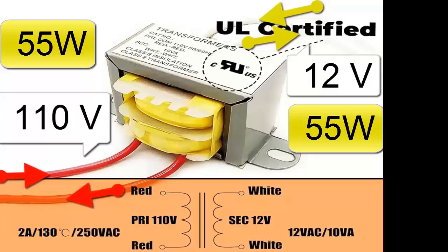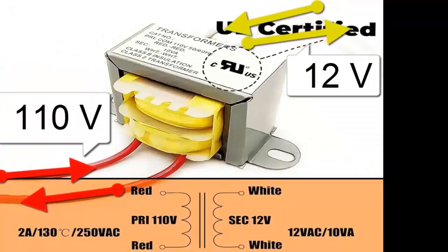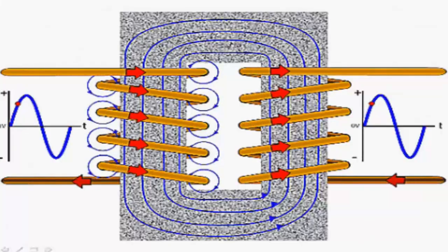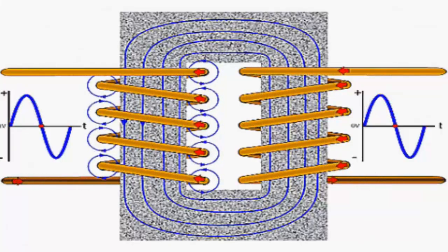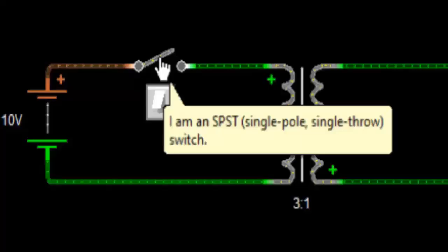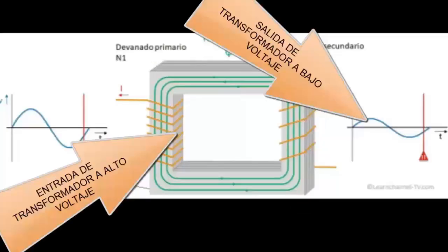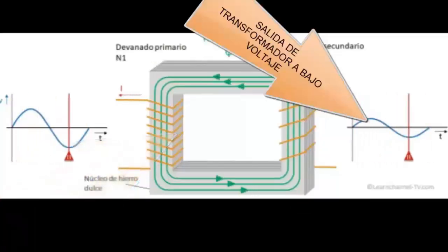The transformer is a device that converts alternating or pulsating electric current with a higher voltage into alternating or pulsating energy with lower voltage or tension without substantially changing the power. The transformer requires the input current to change state constantly, either by being alternating current, which changes its polarity, or by the use of pulsating current generated by electronic control by turning a circuit on and off, so that the magnetic field of that current changes rapidly, and thus an output current can be induced with a different voltage.